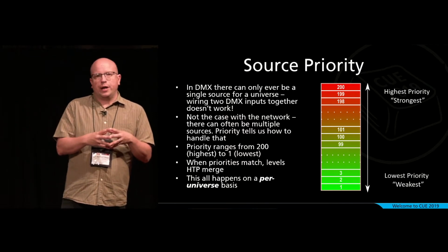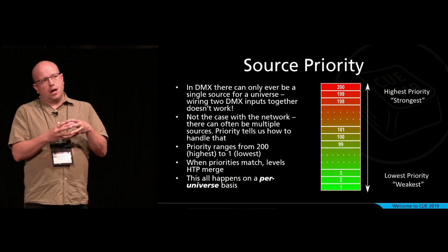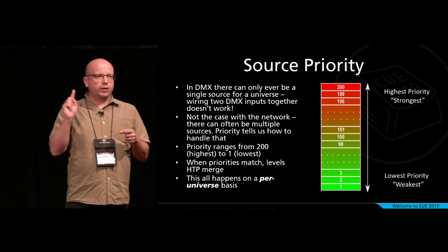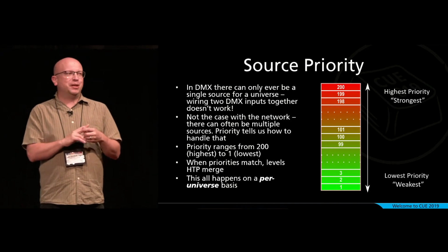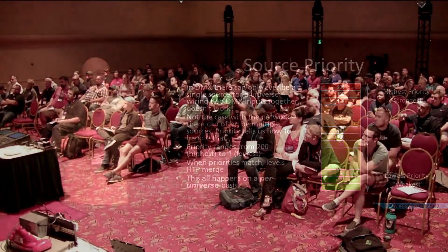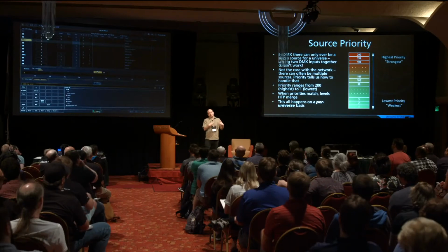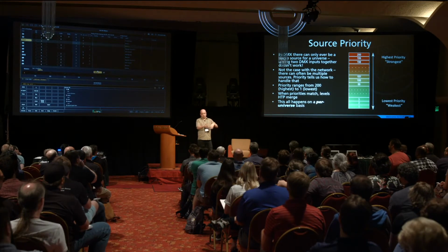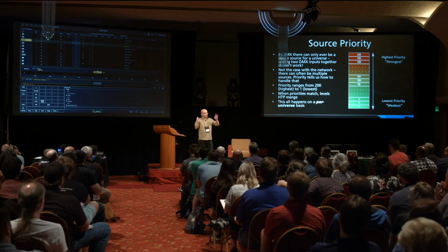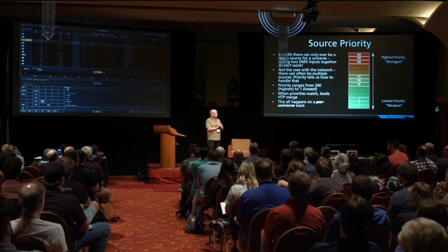So we can also now have multiple controllers. With DMX, there is only ever one controlling device. Has anybody ever plugged 2 controlling devices into a DMX line? No? It's really exciting when you try it. Because essentially they're both sending electrical data at the same time. They're out of sync, so there's just junk appearing on the line, and everything will start flashing on and off. You'll see some really, really exciting effects if you ever try that.